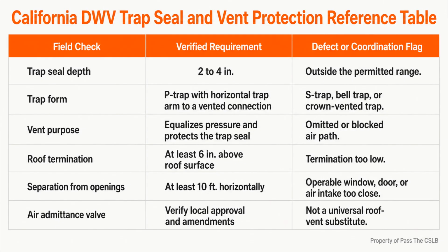If the framing depth cannot accommodate that fall, the answer is not to flatten the pipe quietly. The route, elevation, framing, or approved design has to be resolved before concealment. Uniform grade matters because the drainage system relies on gravity to move water and carry solids. A line that sags creates a low point where material can collect. A line that rises creates an obstruction to gravity flow.